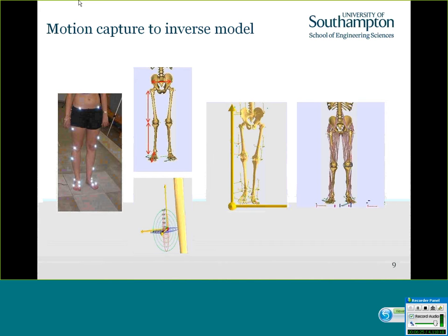And then you also have to estimate the marker positions relative to the model to predict what you have collected within the lab. And certainly there is a definite room for error in the estimation of these marker positions on the model relative to the marker positions captured in the lab, because the graphical representation of the scaled version in AnyBody doesn't necessarily correspond 100% to that taken in the lab.